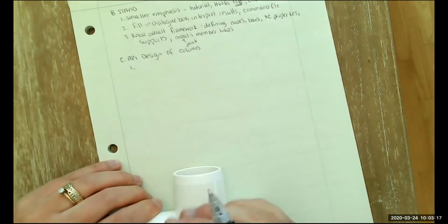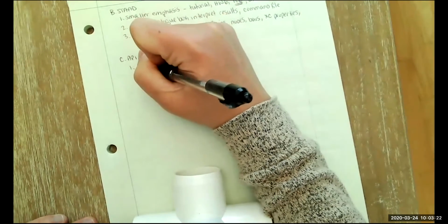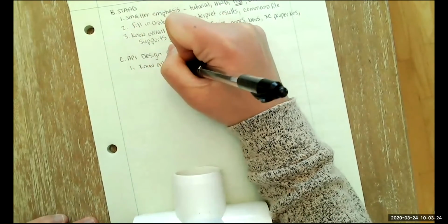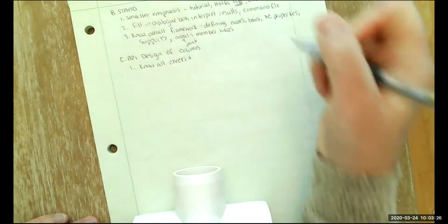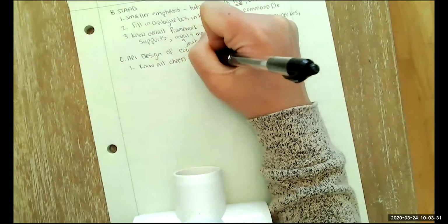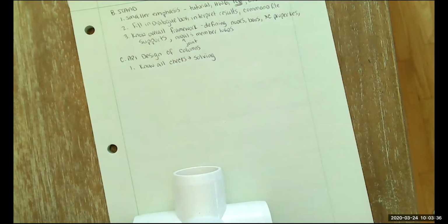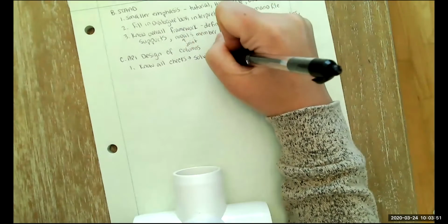Here, I would say, have a look at homework 7 and class 7. It's important to know all of the checks, but also be comfortable jumping in to solve a part of the problem. So if I have already done the axial check and I told you, here's your allowable compressive stress, here's your actual compressive stress, can you do a combined check given information for the bending stress, and knowing what you know about when you have to apply checks for the P delta effect? So, solving parts of the problem.